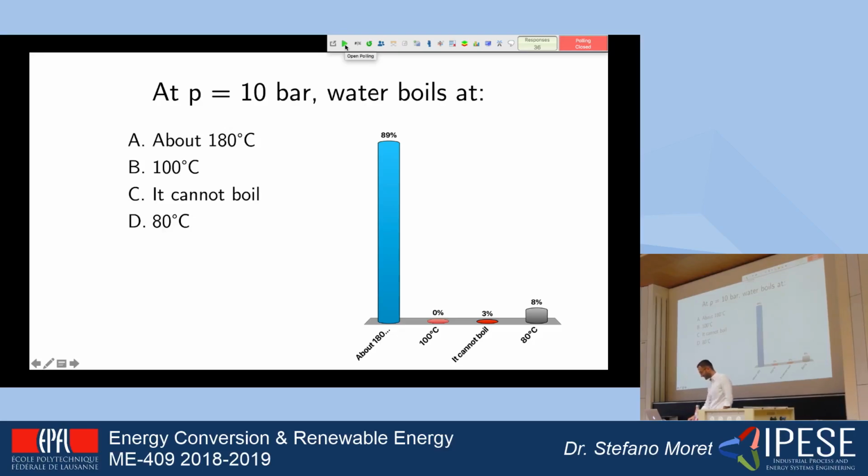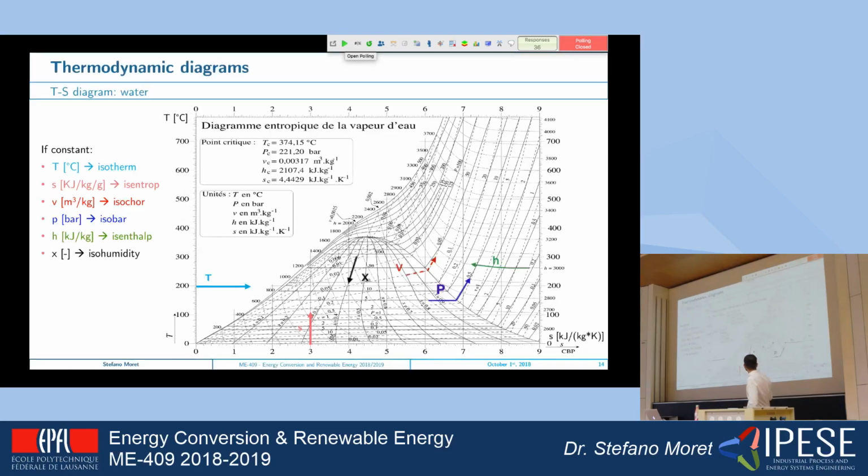Yes, you do. So this is the way to interpret this diagram. What you want to know is that at around 10 bar, the temperature here is around 185 degrees or so. This is the principle when you cook: you have a pressure cooking pan at home. You don't get to 10 bar there, you get to something like 2-3 bars, and then the temperature rises to 120, 130 degrees, which allows you to cook your food faster, right?